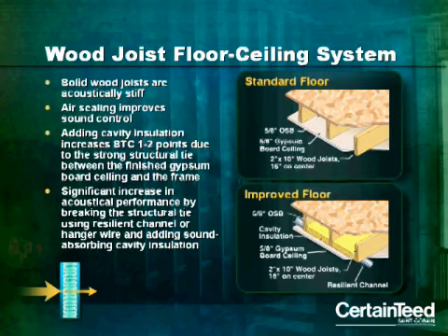We're looking at airborne sound transmission through wood joist floor ceiling systems. Remember, the wood joists are acoustically stiff, easily transmit sound. So air sealing does improve sound control to a point. Wood ceiling joists have more mass and are deeper than wood wall studs. So adding cavity insulation to this space limits the improvement to 1 to 2 points because of the inherent qualities